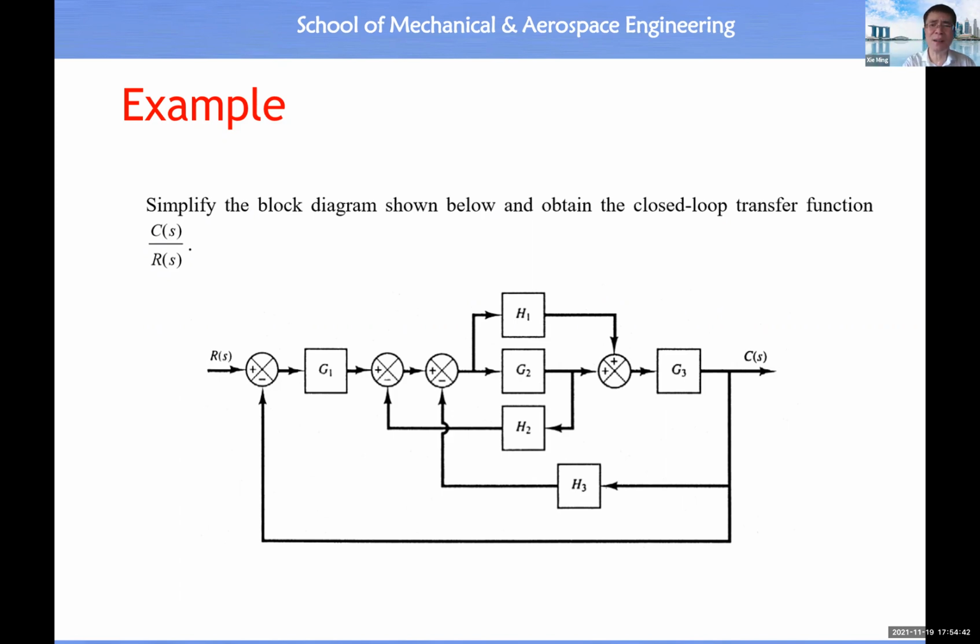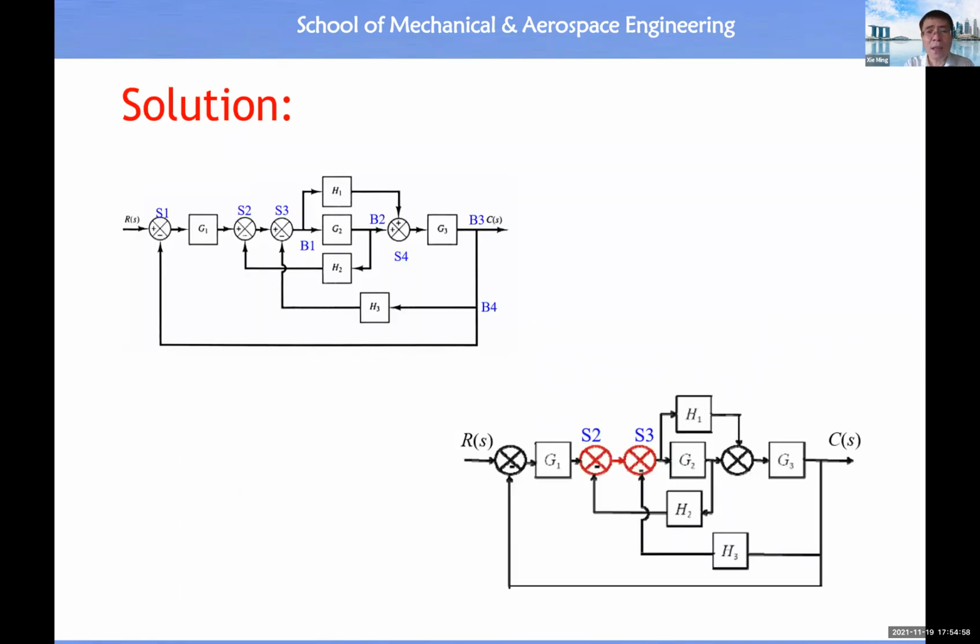So I use this example to illustrate the procedure. Then you understand the power of making use of a Laplace transform, a transfer function, and a block diagram in frequency domain. So first we can modify this local structure. This is a summation, just adding these two signals together. We can change the structure as long as the relationship among the signals remains unchanged.